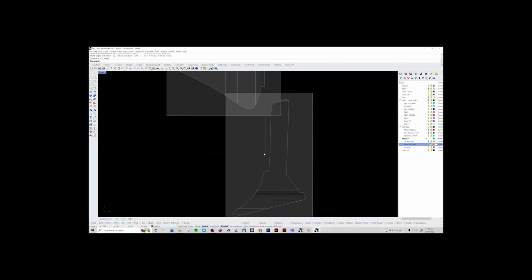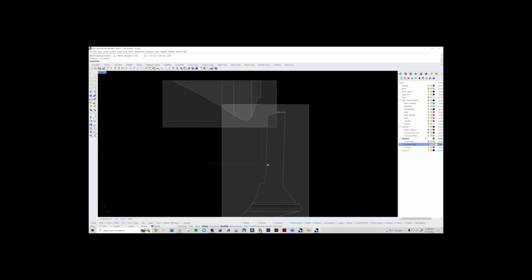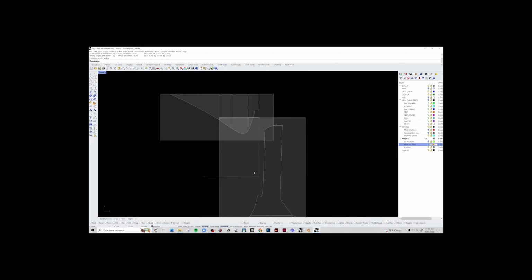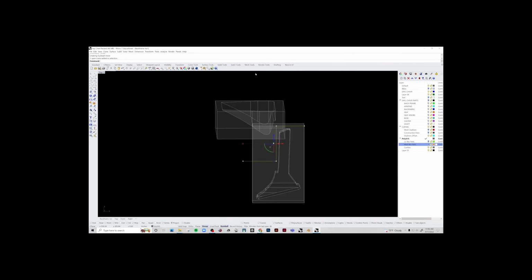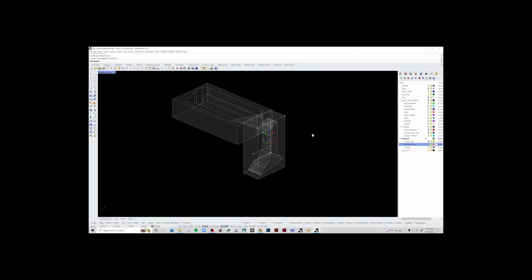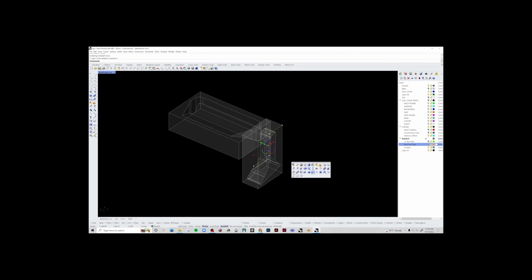And then down here, it's okay if this face isn't exactly where we want it. We might adjust it later, but once we carve it, we can just move that face. And so with this curve, let me just go ahead and move these points up a little bit. Actually, no, let's keep it right there, because we're going to use this to cut through both of these. So with that curve selected, we'll extrude it.